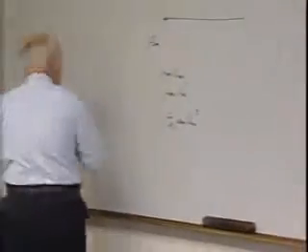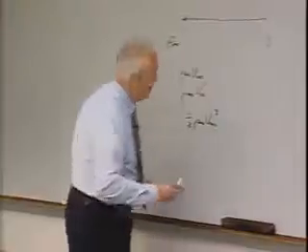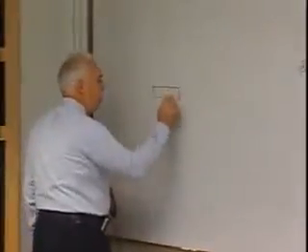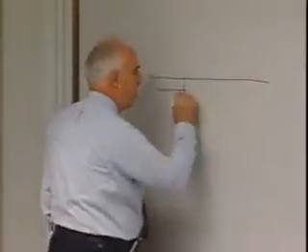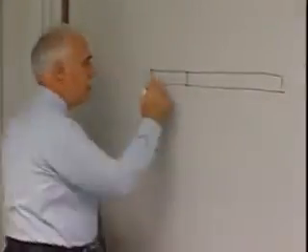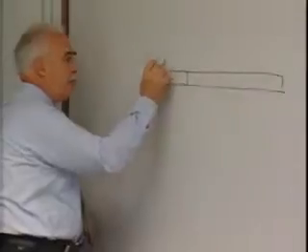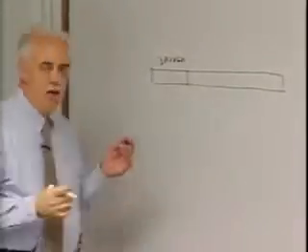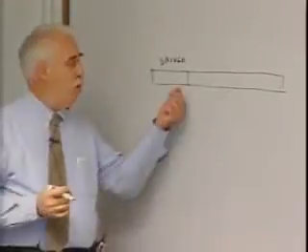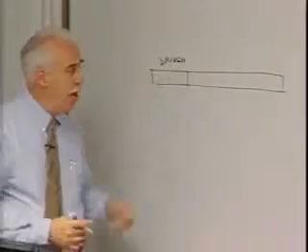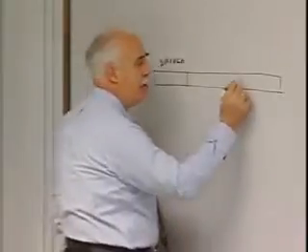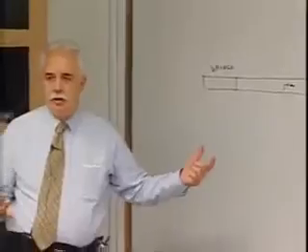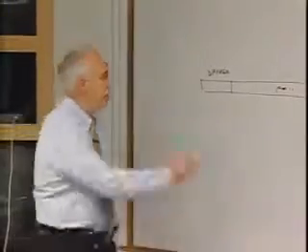Basically, it's a one-dimensional situation just like I've described here, but the way it's generated is you have a driver section and a driven section. In the driver, you try to get to an extremely high pressure with a high speed of sound. Here you have a diaphragm. Here you have, if you want, rho infinity. This is the density that you're trying to test in.